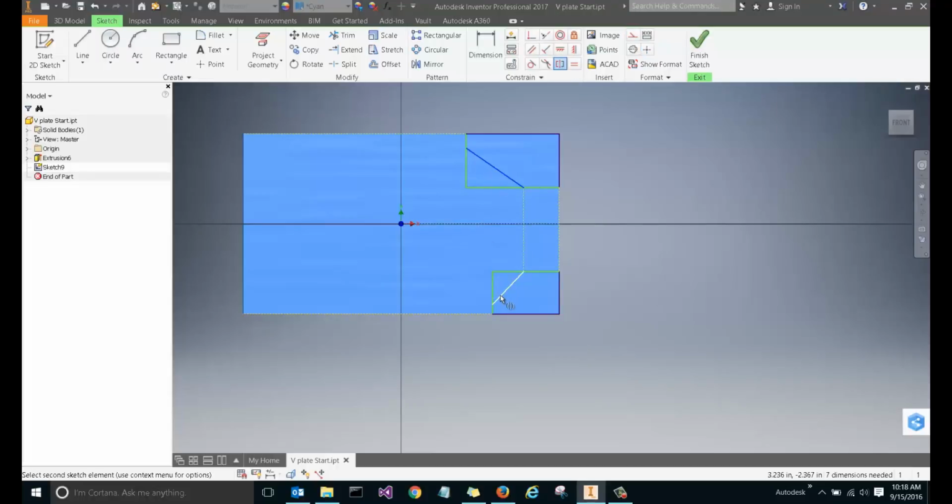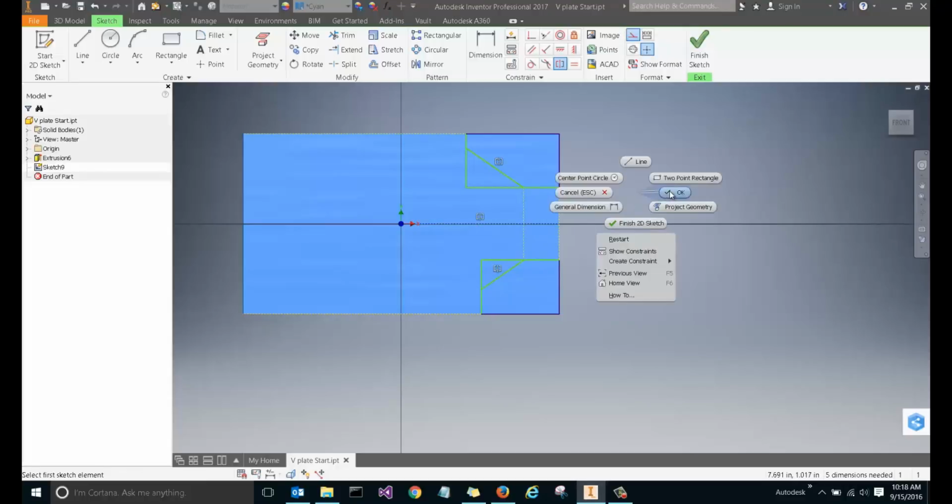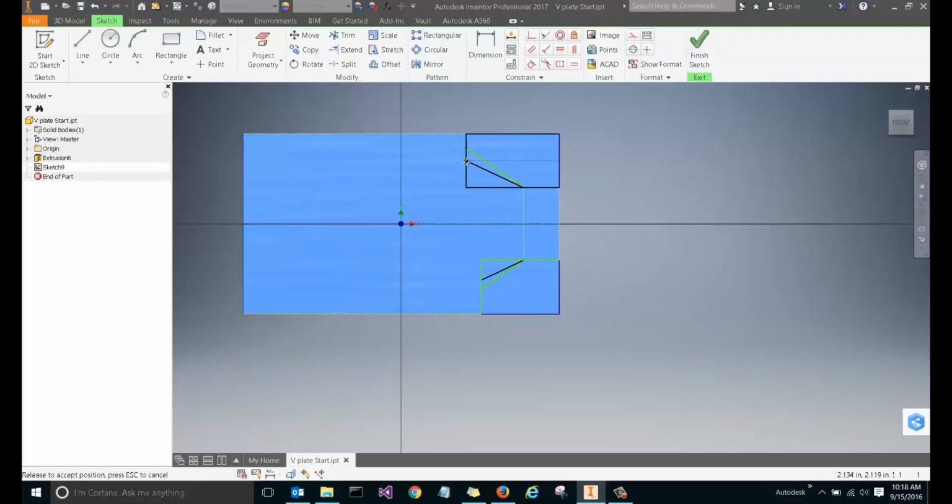So we're going to take the angled lines, select those, and then select the construction line. We'll now see that the angles, as they adjust on either side, will always remain symmetrical to each other. Dragging it from here and there, you'll see that, again, we've added some design intent to this component. Just drag it around to see what happens.